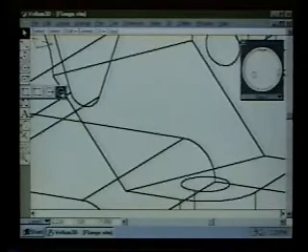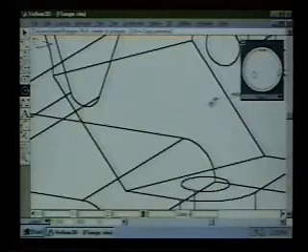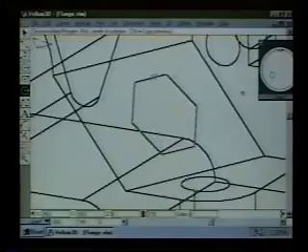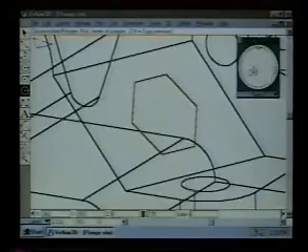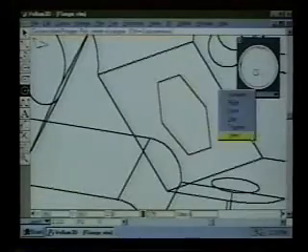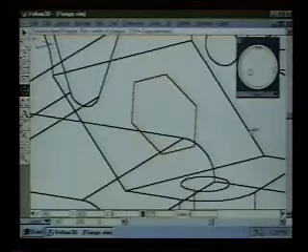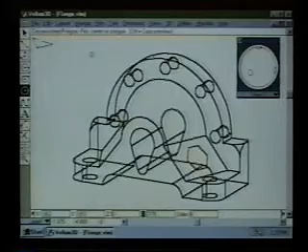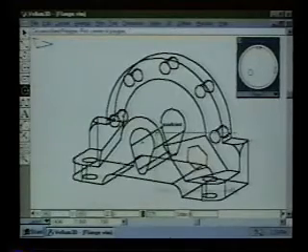For example, if I get my polygon tool, I could grab this point and run right across here. Let's try that. Here's my polygon. I slide right across here, and I'm going to be able to draw a polygon right on that face. And when I roll the trackball, you'll see that sure enough, it's right there on that face. Okay? So when I go back out to view 1, and when I say zoom all, which is going to be in the arrange menu, then let's make a little pocket here. Let's give that some depth.